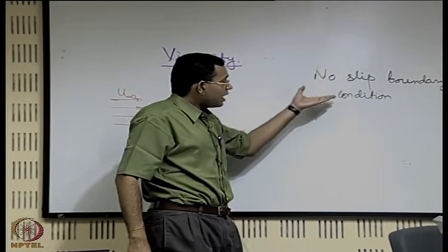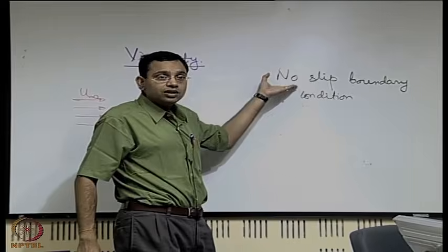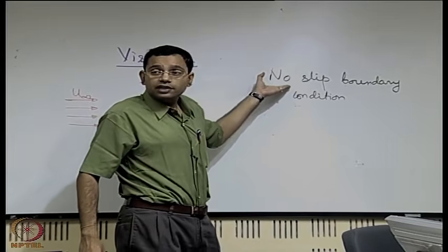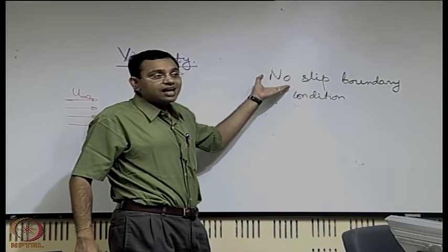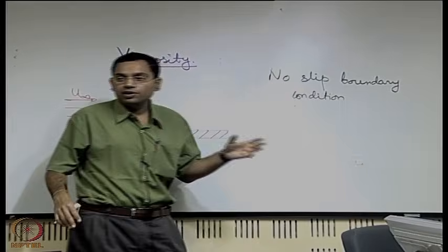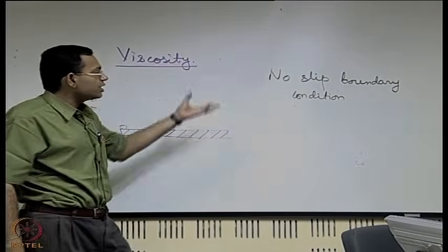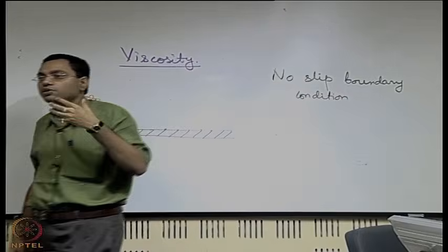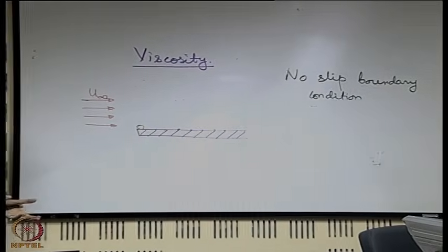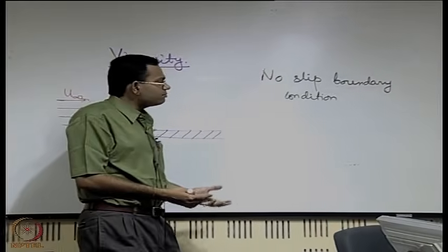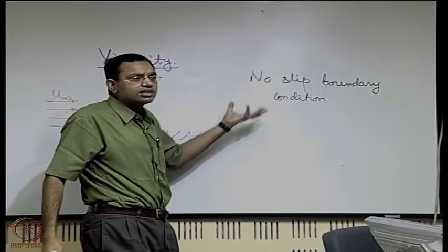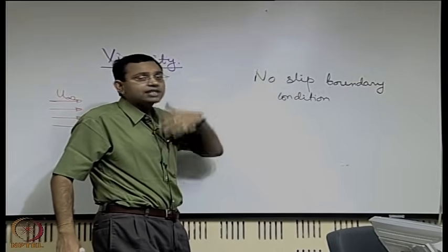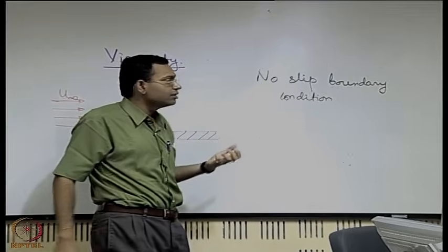Now as I am telling this to you, you are tending to believe that this is always the correct picture, and this has happened really for a long time. For a long time this no slip boundary condition was taken as something like a ritual which should not change. The reason was that for many or most engineering flows it is still valid, or it has been experimentally found to be very accurate.